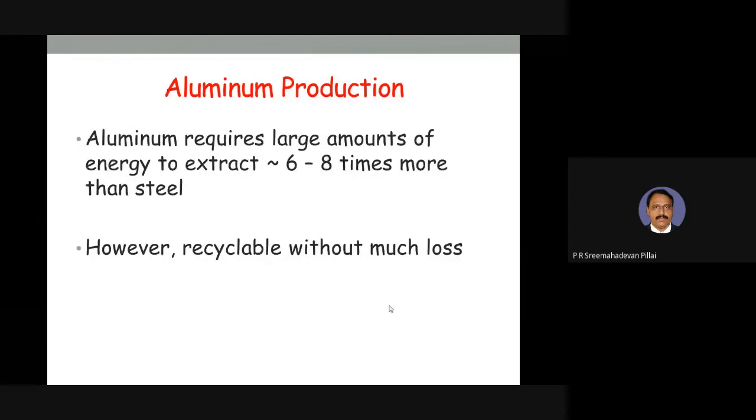Aluminum can be easily recycled like iron. In iron, when you recycle, around 20 to 30% rusted waste may be there. In aluminum, rusting is not there, and even the oxidation is very light, only 1 or 2%. That is the advantage of aluminum. So from the industrial ecology point of view, aluminum is one of the most prominent metals we can use. See the next one.